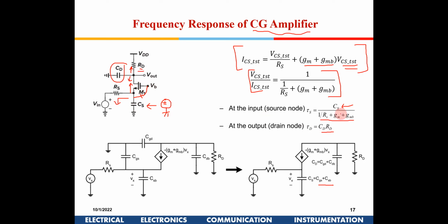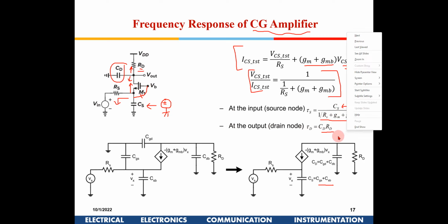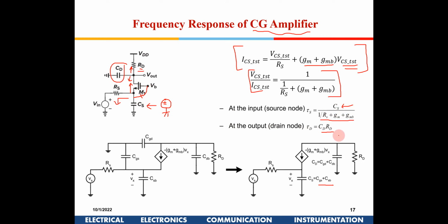Okay. Now you will find that this will have a much higher frequency, because there is no Miller effect out here. Sir, excuse me, sir. Yeah. Sir, you said that there is a resistance RO, right? Pardon? Resistance RO. It is because we are giving the constant bias voltage at the gate. Yes, yes. So when I am looking from the top, it will be an RO when I look into the bottom.